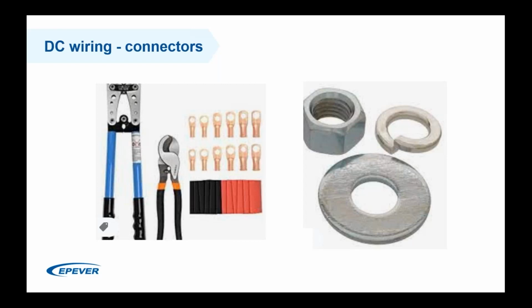So it's better that you apply the same cable length and the same torque and the same sort of connectors, washers, nuts, and springs, and everything should be the same between the batteries, so that all the batteries actually see the same resistance towards the loads, towards the inverter, and the components of the system.